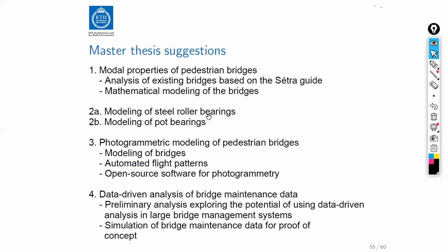Modeling of bearings, I think, is an important topic in railway bridges, because we see that the friction, either rolling friction or sliding friction, can induce actually quite substantial additional damping contributions that the linear theory doesn't describe, and that the current standards don't give any real guidance as to how to use.